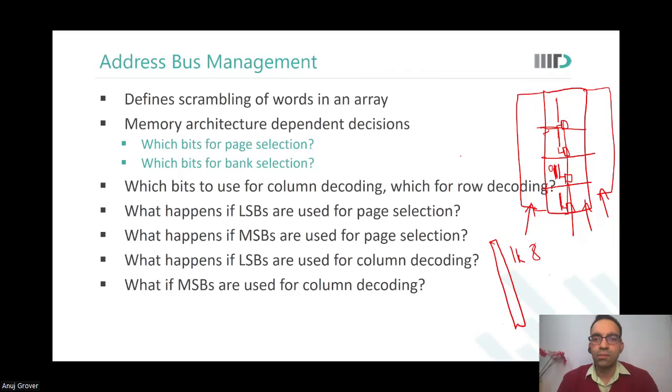So okay, one thing was bit interleaving, that I understood. But what does word scrambling mean? Scrambling means how are the words placed? That's it. You have to place the word somewhere, na? If you do not want to give any scrambling information, you have to place them linearly. The moment you say I will fold the memory and use mux, you need to tell where is which word.